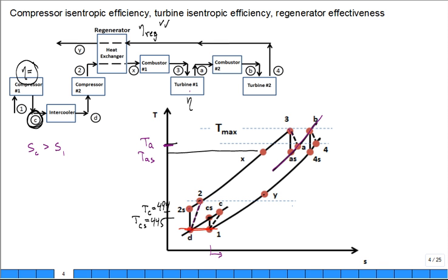And then you got to go to the second compressor. Then you got to go to the turbine. So your work is around there. And then what about this heat exchanger? Well, let me just share something here. I can't walk through this cycle and calculate with the temperature at X without knowing what T4 is. But it's like you start a problem knowing T1 and walk this far, and then you know the outlet condition of the compressor. They tell you the outlet temperature. So walk from the outlet of the compressor through the turbines to get to T4, then come back and analyze the regenerator.